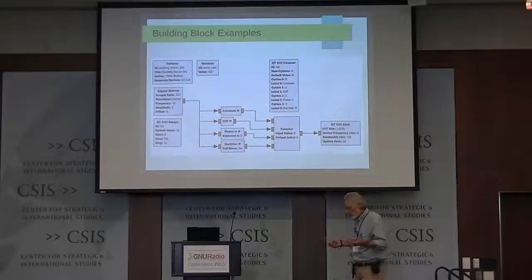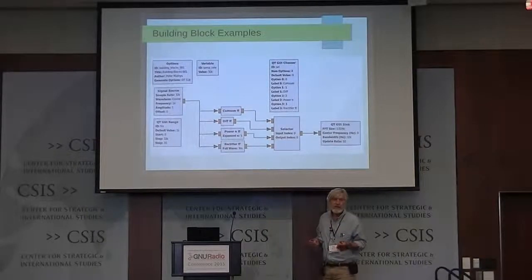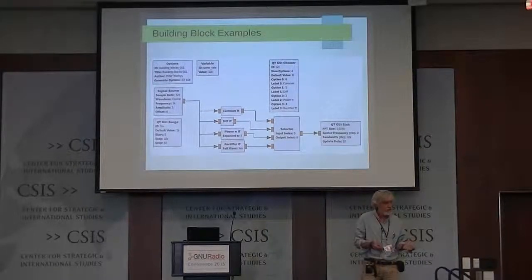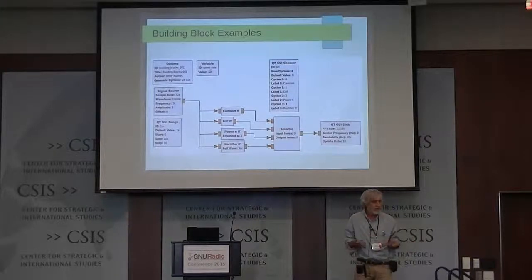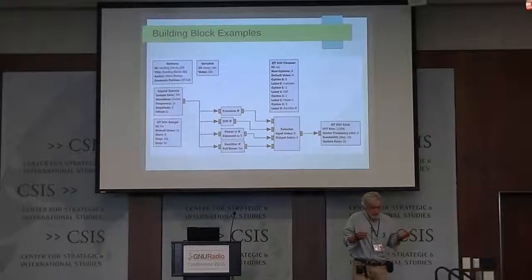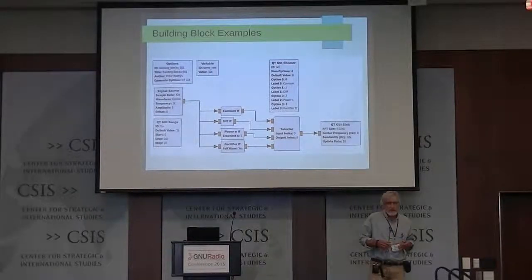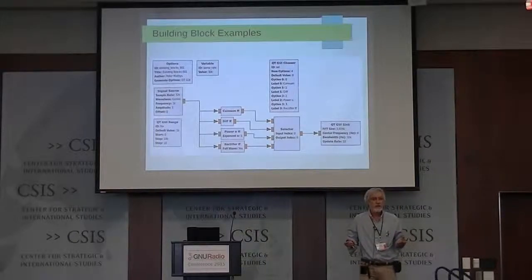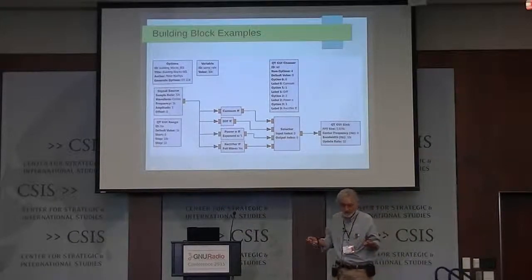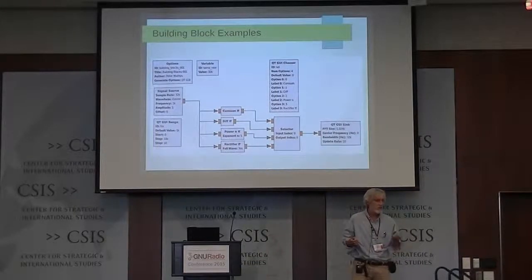And I use that in the beginning of the communications laboratory course because the students first need to learn the difference between analog and digital, or actually I should say discrete time and continuous time. Because in the sampling theory they have just heard that there is such a thing as the Nyquist frequency, so if I give them a 1 kilohertz waveform, then they think I just use a 2 kilohertz sampling rate and that will do the trick.